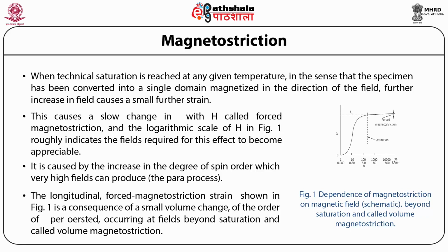When the sample changes shape, so does the grid, and the change in shape causes a change in the electrical resistance of the gauge. With ordinary gauges, the fractional change in resistance is about twice the elastic strain.